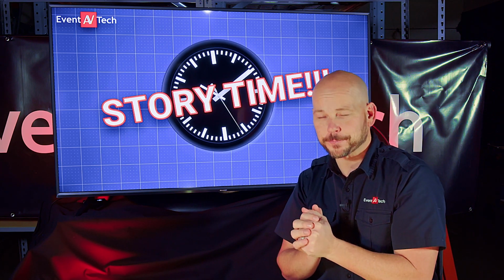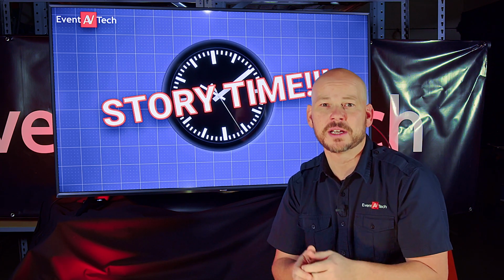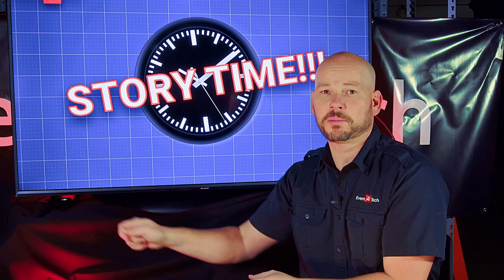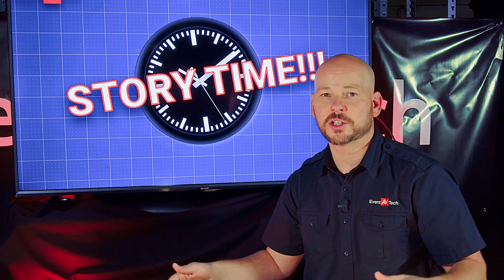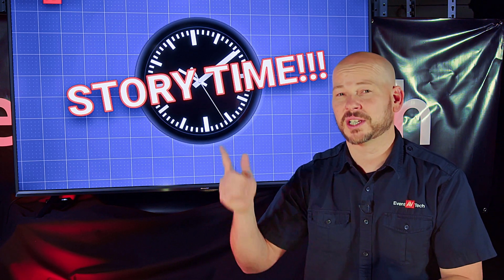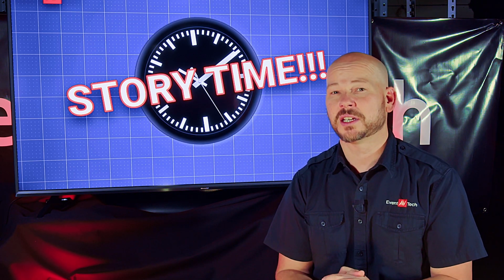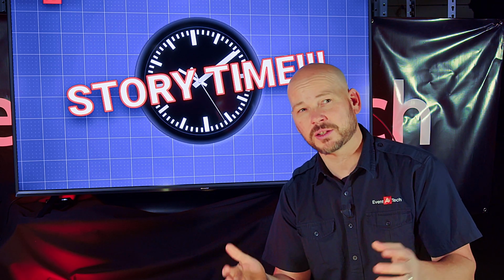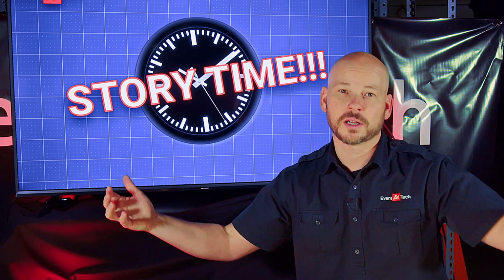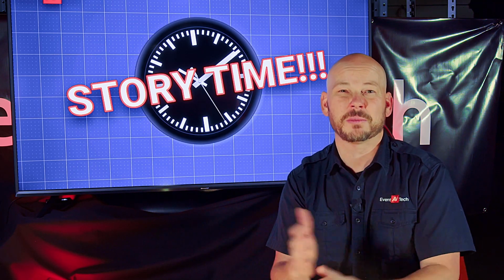And I said, well, your entire sound system is gonna be inside panel 1. And she was like, well, how do you know that? And I said, well, because you're on stage, that's where you plug your dimmer packs in. All of the stage power should be in the same panel box. And I said, my guess is your performance lighting in the air is going to be in a different panel box. She said, well, I actually installed that too. That's in P4. And I said, well, all lighting should have been in P4 and all sound should have been in P1. That's how they're keeping the separation.